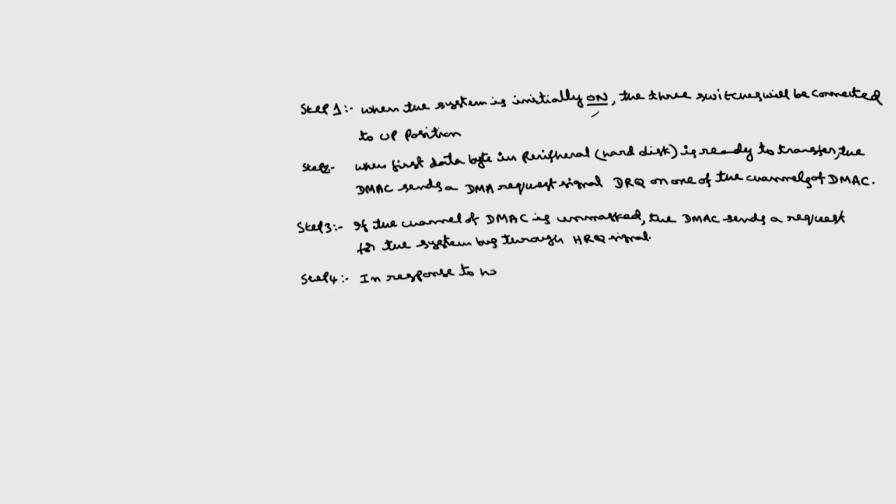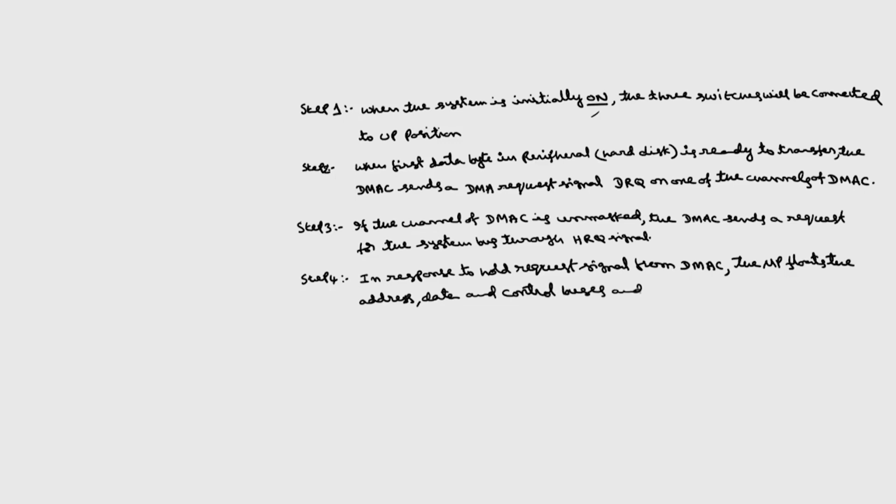In response to hold request signal from DMA controller, the microprocessor floats the buses, address, data and control buses, and sends the hold acknowledge signal to DMA controller.